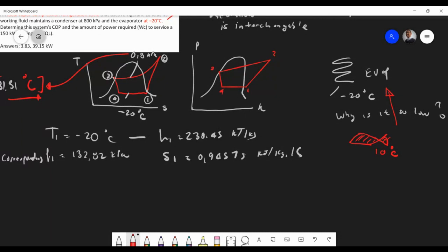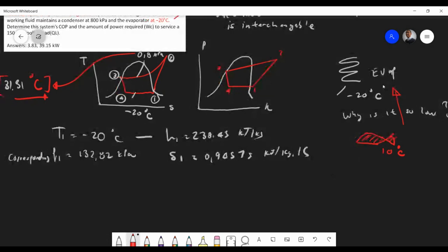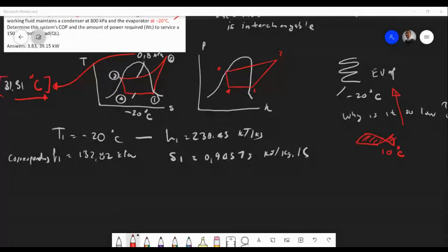So we need the temperature of the refrigerant to be low for two reasons. The first is to absorb the heat of the fish, and also we want a low saturation temperature so it can boil at atmospheric conditions. Is it clear to everyone? I'm just trying to include lessons in between.